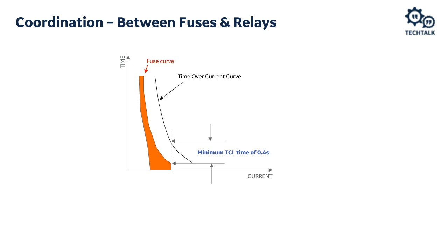Now in a few minutes we'll go through why we think this should be around 400 milliseconds, but you want some time. And there are a lot of things going on there with relays that we need to coordinate some time with. Now one of the things about fuses is that the fuse itself will be subject to manufacturing tolerances.